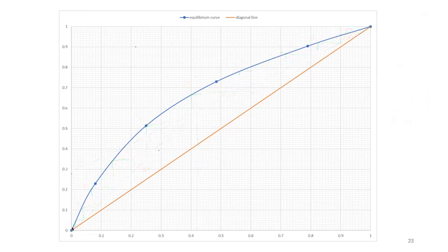Okay, so for part C, you are asked to take into account the Murphree efficiency. So what you do is, this is given the VLE for the blue line. Okay, you plot your ROL, SOL and Q line as previously. So let me just try it again this time. That's 1 point for the ROL. This is another point for the ROL. So I try to connect these 2 points to get one nice straight line.